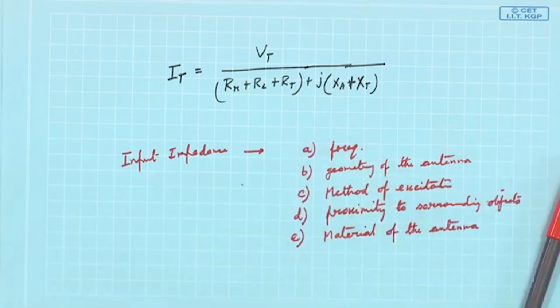So, we have seen how to model, even in circuit theory, this antenna. That is a nice way that we started, from the current element, the analysis from field theory. Once we have known that, field theory gives us all the information, and from that if required, when we are connecting the antenna with a transmitter or with a receiver or load, we can model the antenna as a circuit theory object.